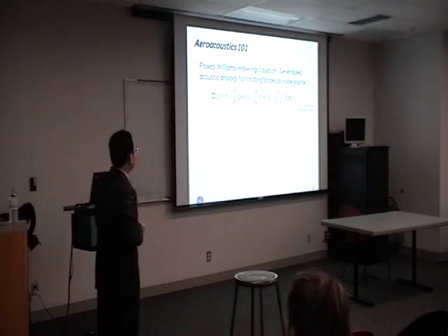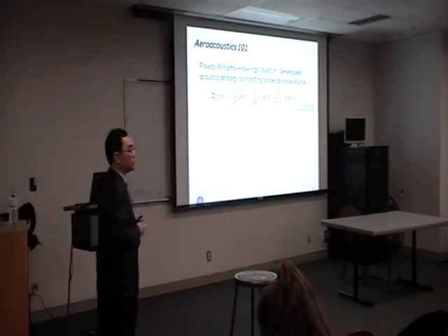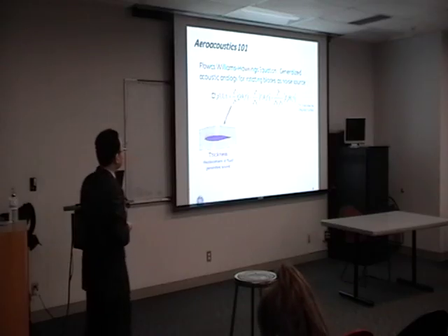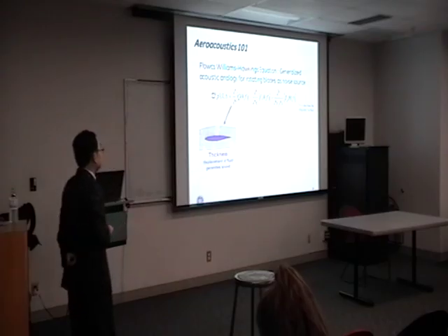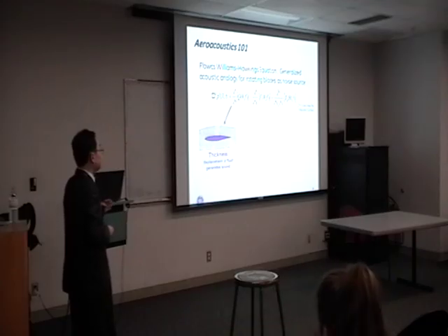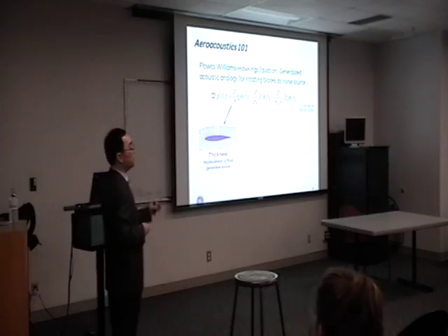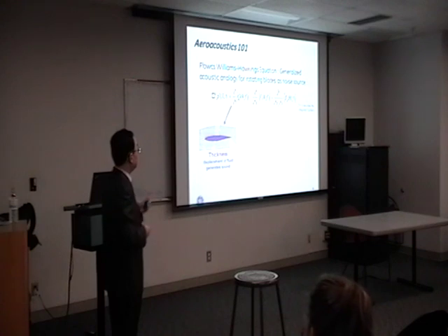The left-hand side is a wave operator with respect to acoustic pressure. The right-hand side is the acoustic source term. The first term is called the thickness noise. The noise is generated by displacement of fluid because of the motion of the body. If the body is stationary, there is no motion, and this noise is not generated.